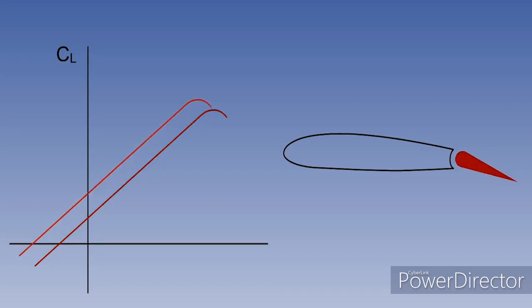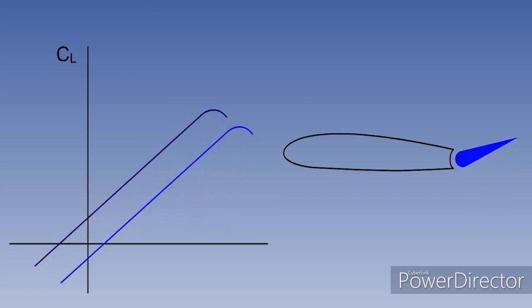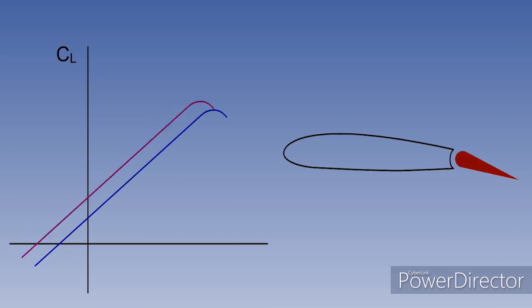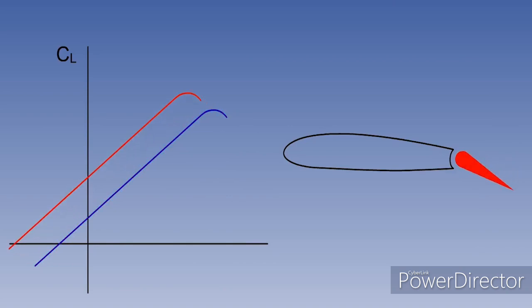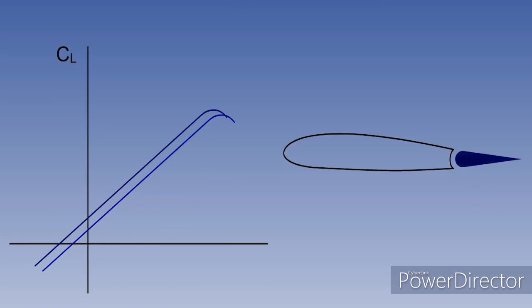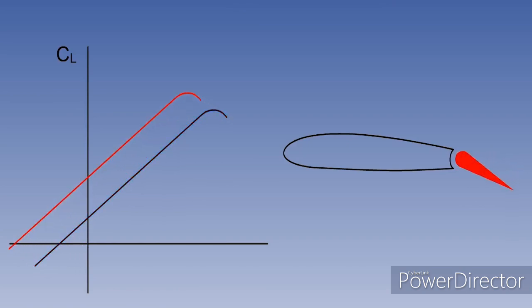The basic method of changing the attitude of an aircraft, that is, its position relative to the horizon, is by temporarily changing the camber of the aerofoil of the wing, tailplane or fin, which will alter the lift it produces. The diagram shows the change in lift with changes in control surface position. The overall effect of a control movement will also depend on speed.